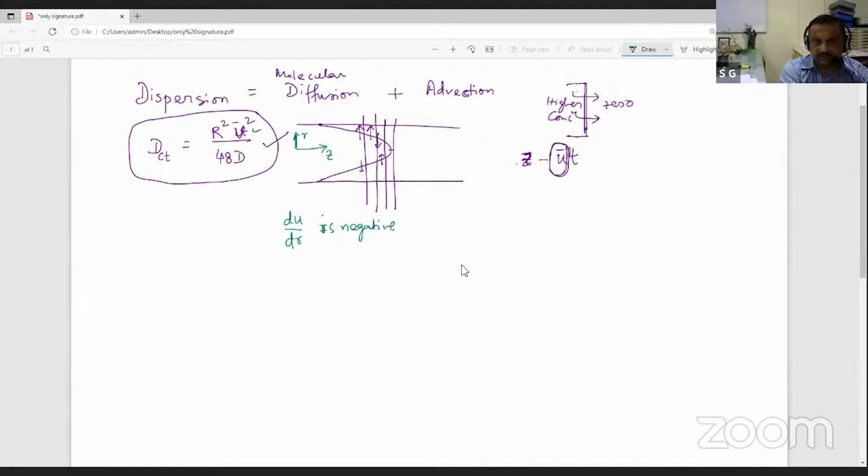And when it comes to the definition of tau, you may recall that I have mentioned tau rx in that derivation. So tau rx means r is the direction of the plane on which the shear stress acts, and x is the actual direction in which the shear stress is acting.